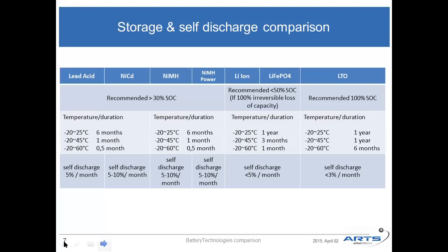That's why you can store them for 1 year or even more sometimes in standard conditions. But don't forget that sometimes you have electronics in the battery pack, and sometimes electronics in the device, that can consume current. In that case, you have to take into account that those values are only valid for the cell. That means if you add electronics, you have to add their consumption.